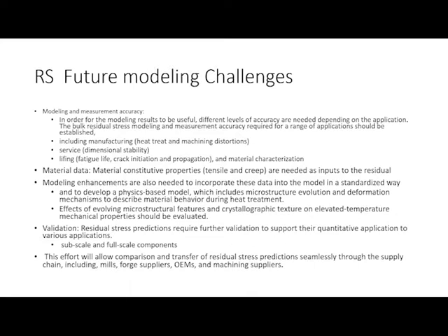And then the bottom line is lifing. And that is the one area where we really have got to improve our tools so that we can better predict this improvement that residual stress will give us, and it has to be both in the initiation and propagation. And we're going to need to be able to take those models and also incorporate both tensile and creep, because obviously in a turbine engine, you're spinning, you're exposed to air, so there's a tensile stress. And because it is generating combustion products, it's going to be exposed to temperature.